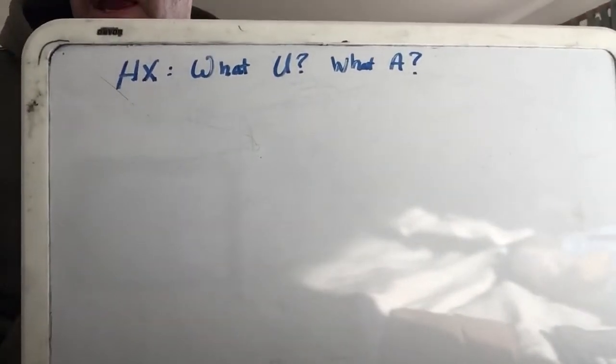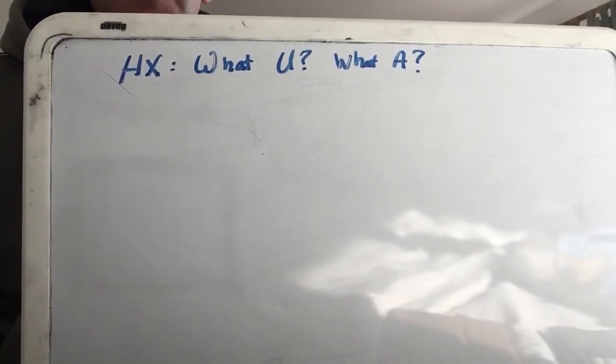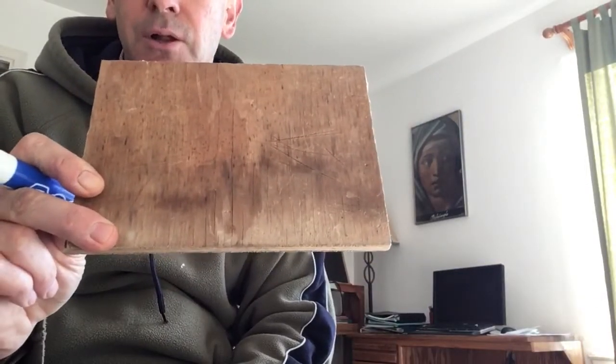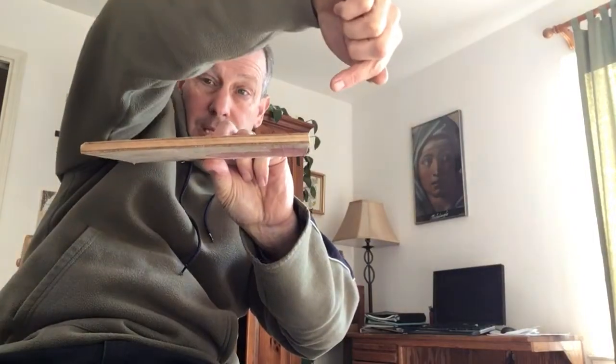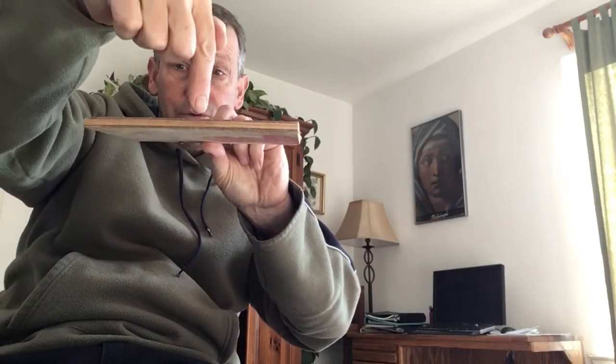So, in short, when you have heat exchangers, probably the two main questions we have is, hey, for a heat exchanger that we're thinking about, what's the U and what's the area? So, the simplest type of heat exchanger would be a flat plate heat exchanger. So just imagine this is a sheet of metal, and we got a situation where we want to exchange heat between two fluids, two flowing fluids. So a good example would be we want to cool down engine oil with water. So what we want to do is separate those. We don't want the water and the oil to mix. So we could have this oil come in here like this. There would be an opening here and a passageway for the oil to go through, and then we could have the water flowing on the bottom, and then heat would transfer down from the oil to the water. And that way we get exactly what we want. We get heat transfer, but at the same time we don't get the fluids to mix.